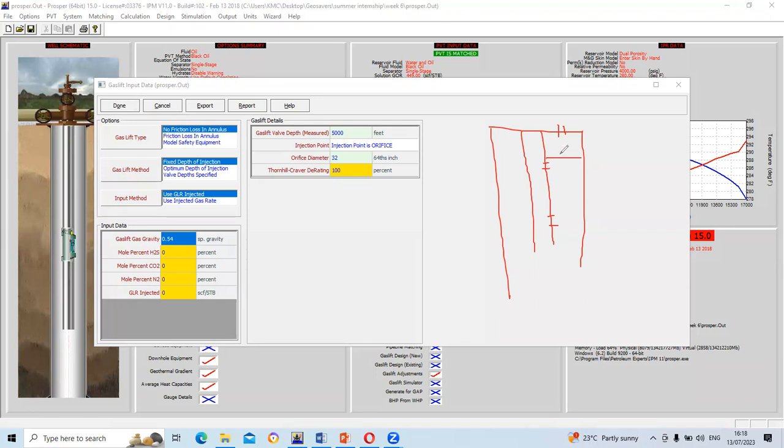But immediately the pressure out here becomes higher than the pressure inside the tubing, this valve is going to open and fluid will flow. So they will pump the gas at high pressure. As the gas is forced down, it increases the pressure inside this annulus. Then the pressure here becomes greater than the pressure here. So this valve will open and this fluid will easily flow